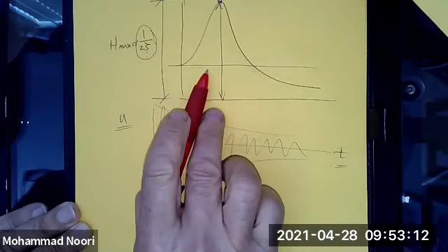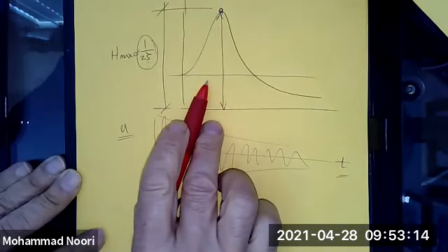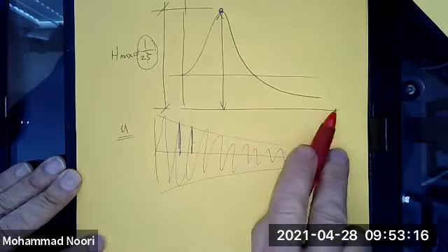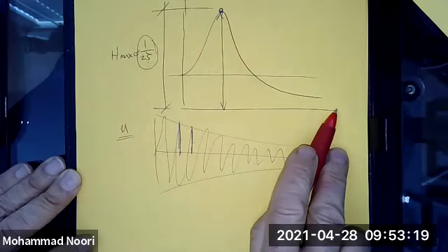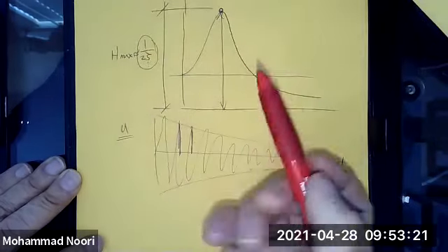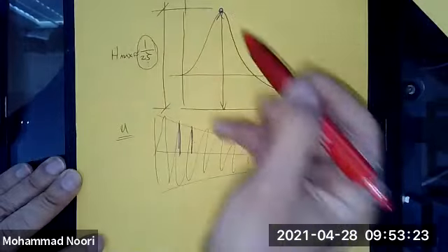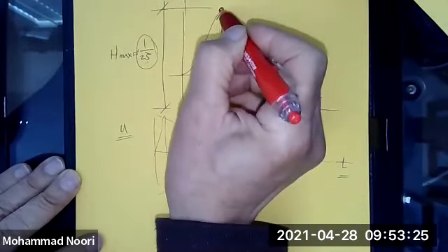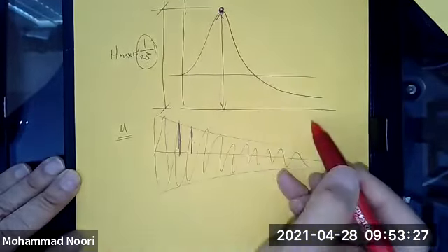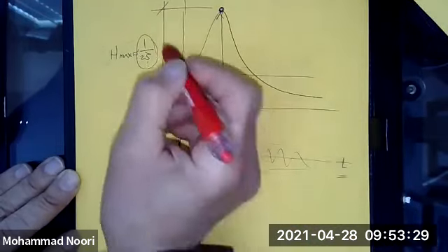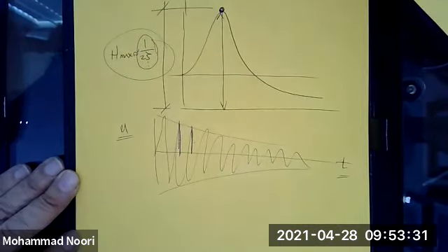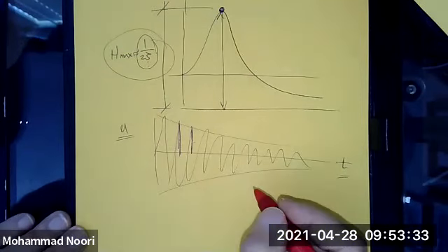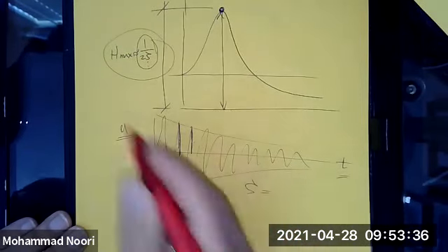Whereas by plotting a frequency response function, you have a nice and clean curve, relatively speaking, because you always have noise. But it's easy to measure the peak value of this curve, and then you can quickly find the damping ratio, because the damping ratio is what?